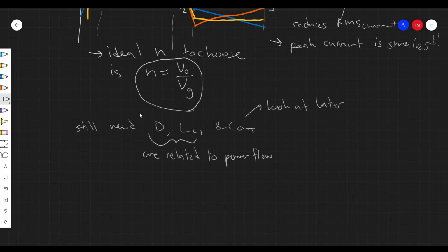So this is really the range of D, right? So we have two limits on our current, right? So again, Iout varies from 1 amp to 10 amps, right? And we also have this equation. So we're going to have some D, I'll call it D2 for the 10 amp case, and we're going to have another D, I'll call it D1 for the 1 amp case, right? So we have this range of D.